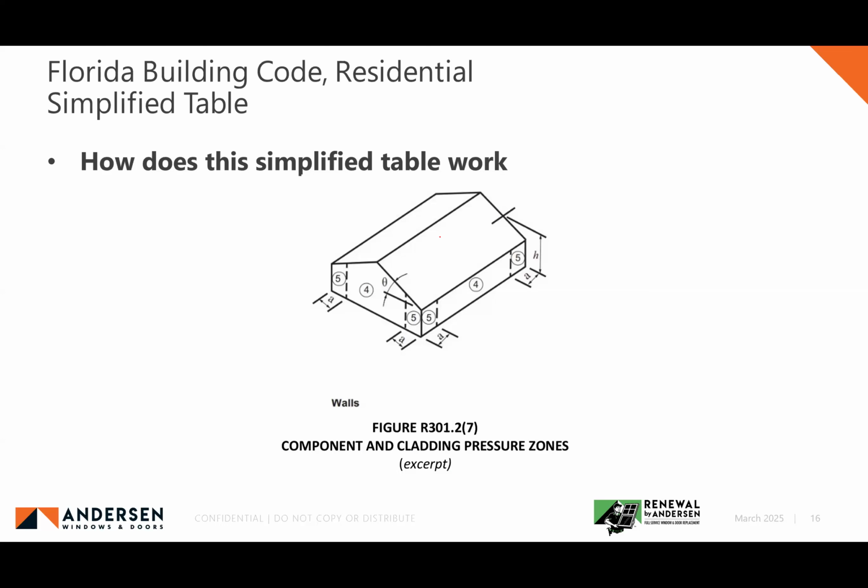That width is in and of itself a pretty complicated variable to determine, because it's based on the geometry of the building, but 3 feet is the minimum in ASCE 7. In the IRC, we say take it at 4 feet. So anything within 4 feet of a corner.